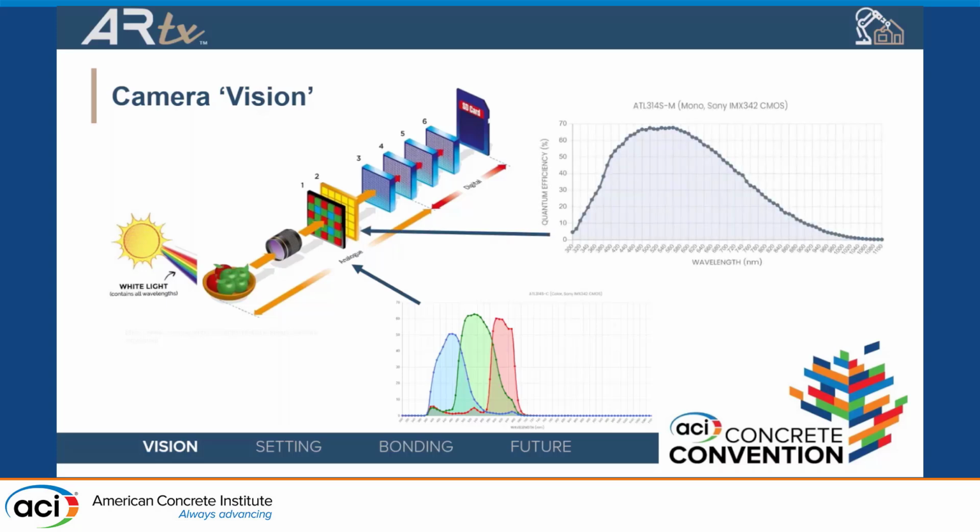And the other part is a sensor array, which takes the photons that are let through the color filter array and changes them into electrons. The efficiency with which it does that at every wavelength is called its quantum efficiency. So for a color camera, this is a typical quantum efficiency with an overlay of the band passes that are involved. For color cameras, the chemical used as the photodiode to change photons to electrons is silicon, but there are plenty of other sensor chemistries out there that react differently in different parts of the spectrum.